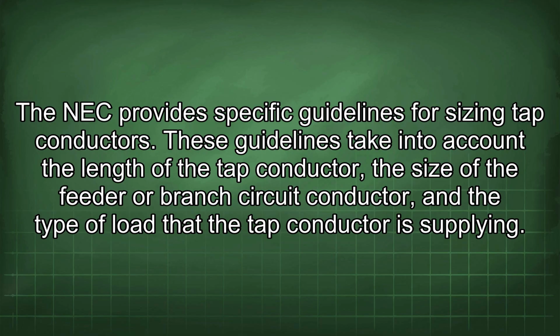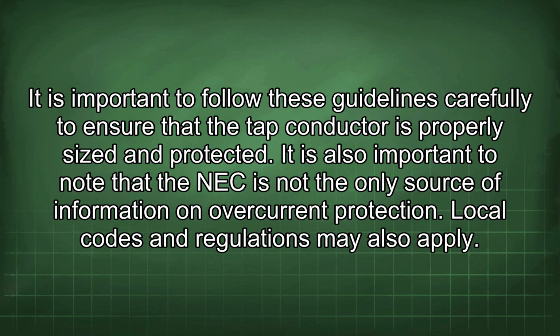These guidelines take into account the length of the tap conductor, the size of the feeder or branch circuit conductor, and the type of load that the tap conductor is supplying. It is important to follow these guidelines carefully to ensure that the tap conductor is properly sized and protected.